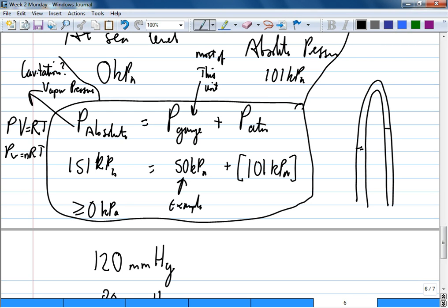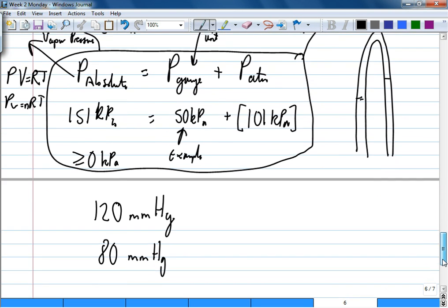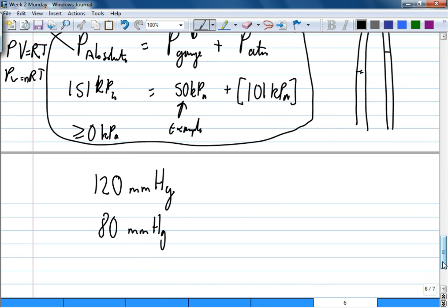They measure vacuum pressure. Vacuum pressure doesn't mean that it's 0, but pressure below atmospheric. Some gauges, especially those used in refrigeration systems, actually go down to -1 bar. You cannot go to -2 bar because that violates this rule here. So you see some gauges actually go to -1 atmosphere, which enables you to measure negative. Here we assume this one is positive, nobody is leaking air inside.